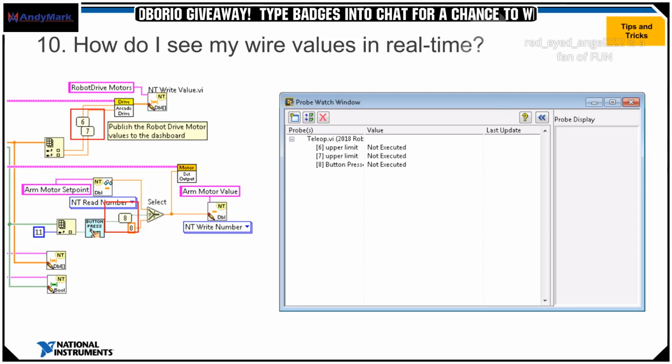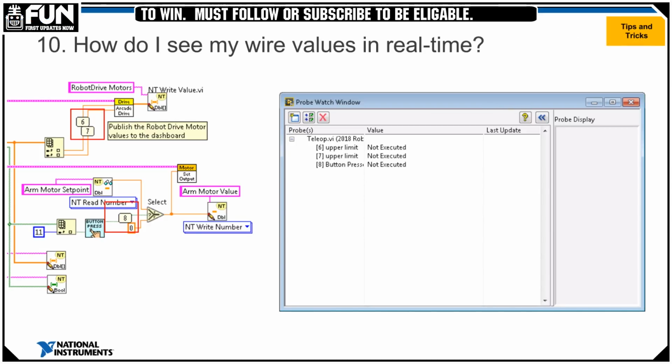And periodic tasks is going to start running as soon as robot main starts running. And robot main starts running as soon as your robot turns on. So you'll immediately start getting that data as soon as the field management system starts returning it to the robots, so you can start making actions on it at t=0 when the match starts. So I would put it in periodic tasks.